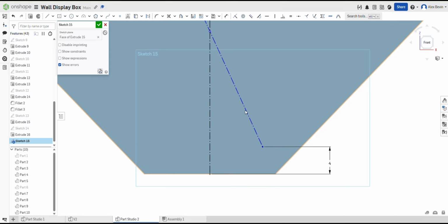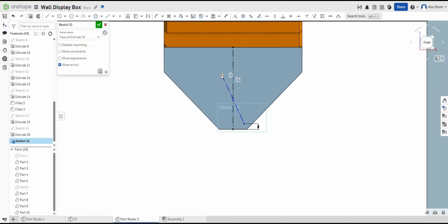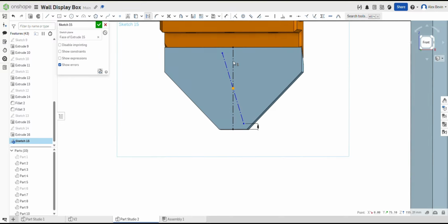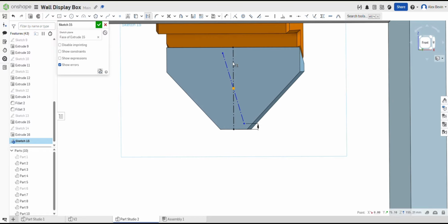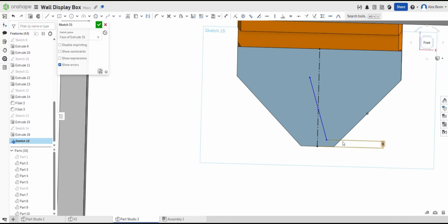Important, set your merge scope to the bottom cleat only. That stops the hole tool from accidentally drilling through other parts. For the hole settings, hole type is drilled. Drill size is 5 mm. And termination is through all. Through all is best here because it's future-proof. If thickness changes later, the hole still works.